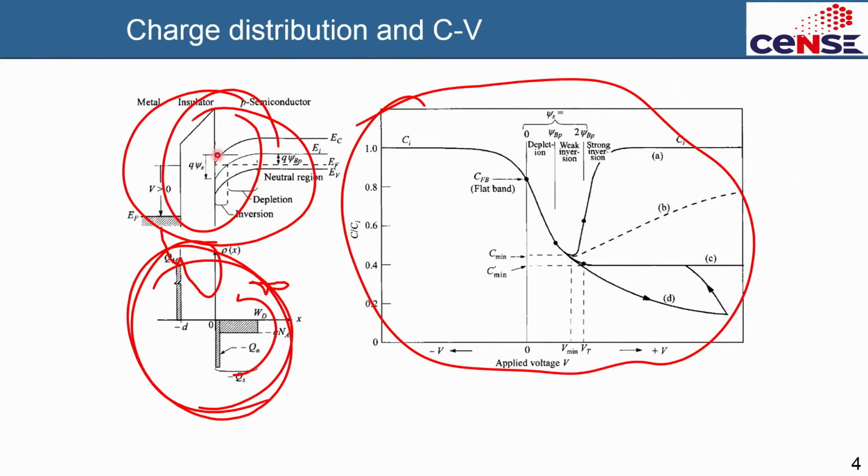And once the inversion layer forms here, I told you the depletion that is extending here is the maximum that you can go. So this is the maximum depletion. So your capacitance will be minimum, and the value will stay minimum for a high frequency curve, and this is the curve there. Okay, if your signal is changing very slowly, then minority carriers will get enough time,